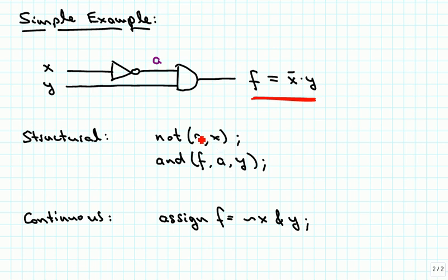So when we specify this here, the first element in those gate specifications is the output of the gate, and then the rest of it are the inputs. So here are two inputs for the AND gate, one input for the NOT gate, and we could make an AND gate with 3, 4, 5, however many inputs that we want by just adding more in the description here.